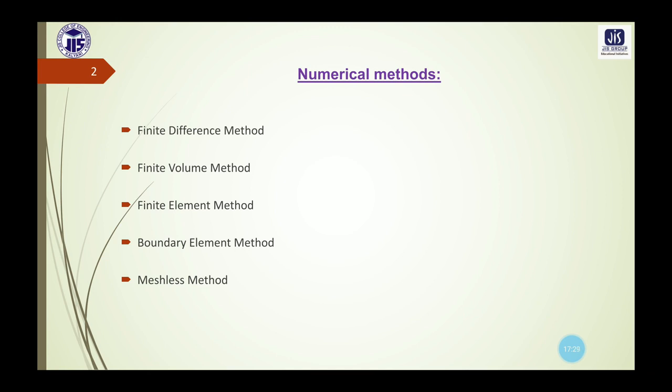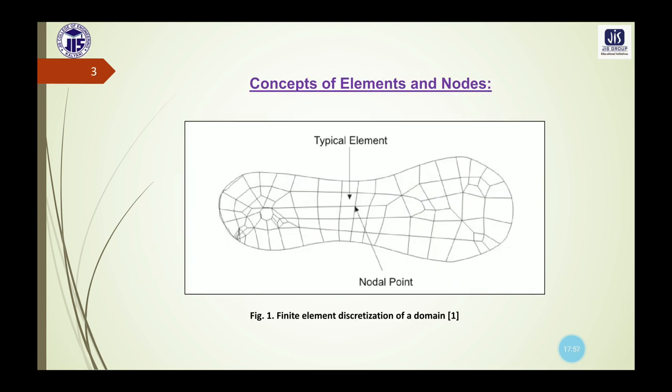In this finite element method or finite element analysis, a body or a structure having complex shape, in which the analysis will be carried out, is subdivided into smaller elements of finite dimensions called the finite elements. This can be seen in this diagram also, that this complex shape is subdivided into smaller elements of finite dimensions, which are known as the finite elements. Here it is shown as a typical element, one almost rectangular shape structure, which is a subdivided part of the total complex shape.